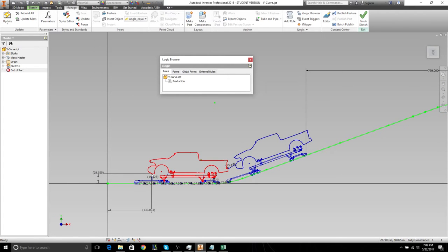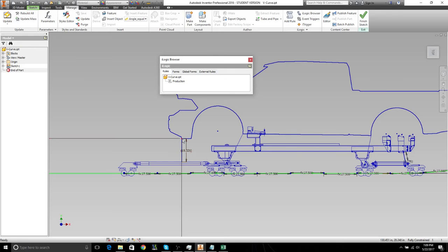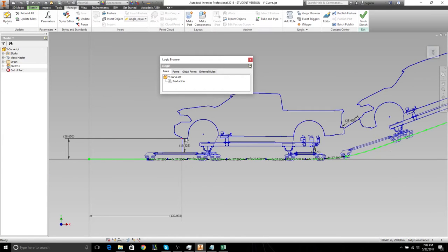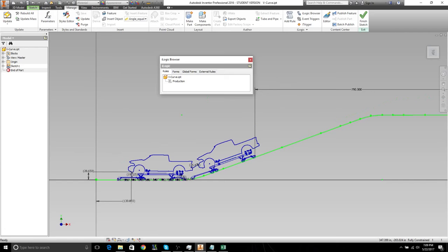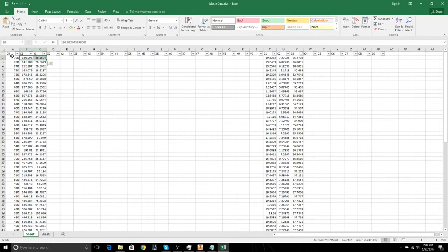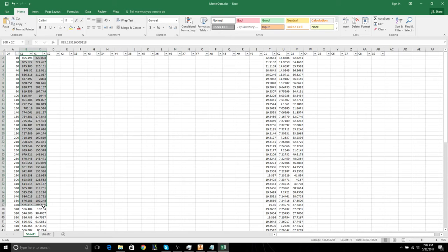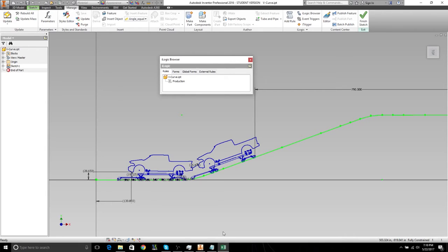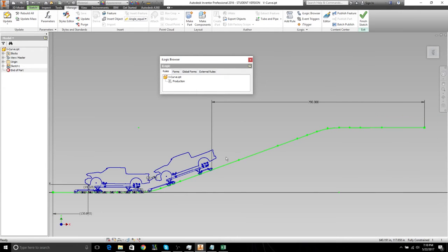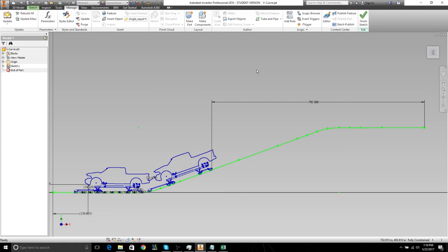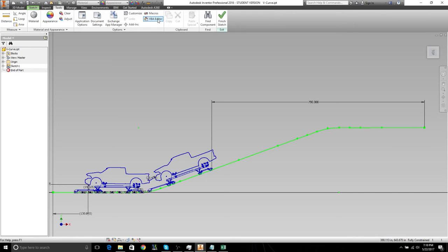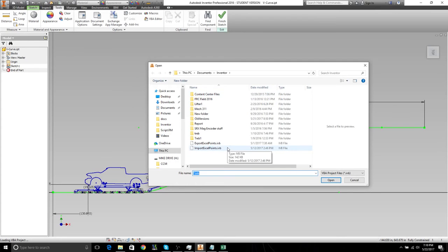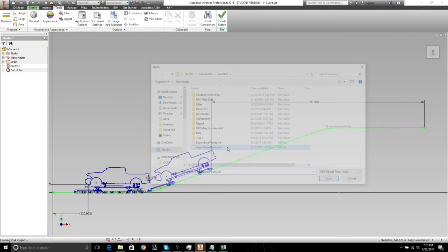So now we're going to take a look at this point of interest here, which we wanted to analyze throughout the entire curve. So that data, that XY data, got exported here, and if we sort by driver value here, we can see that in order. And right now we want to show the path of that motion. So since all those points are available to us, we can implement a macro that we've already used. So if we go to the Tools tab, the VBA editor, load project, import points as we did in the curve setup.